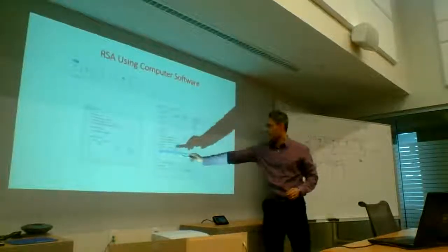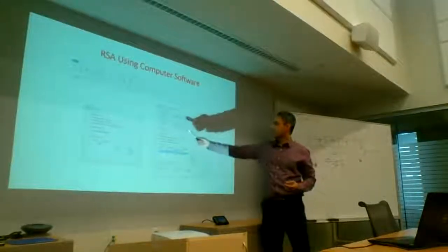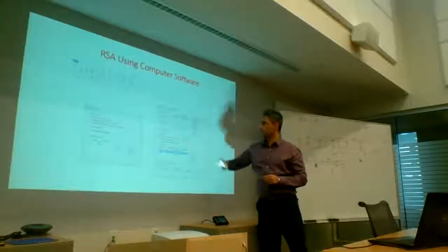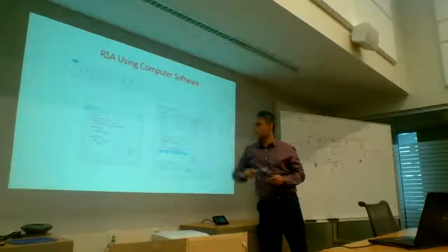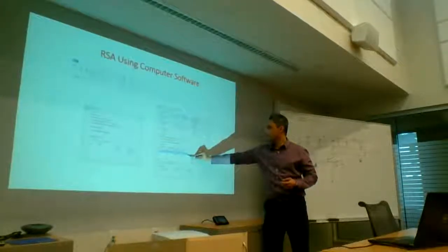So here you see how I do the 100%, 30%. I have got this modal combination as CQC. I know it's hard to read, that's why I'm reading it out to you. The modal combination is set as CQC. And here is where I'm adding them.